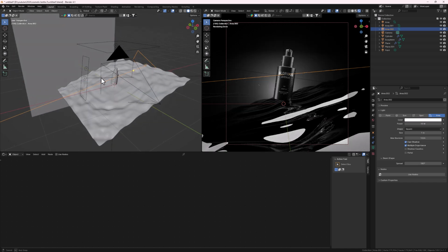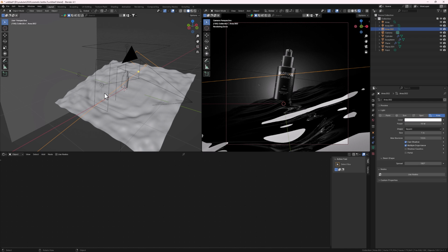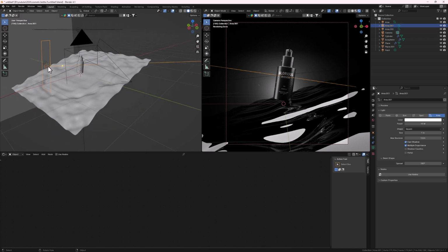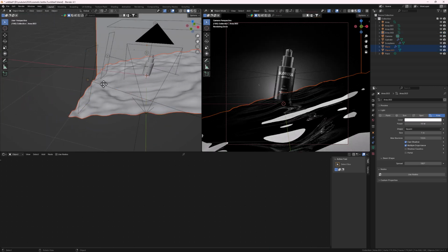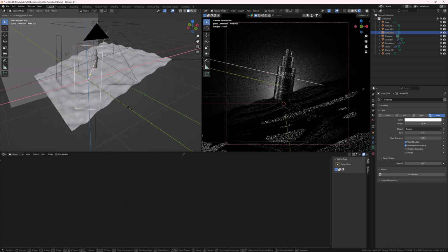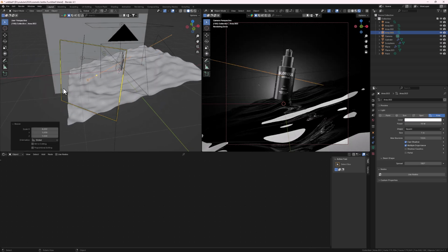Then maybe we can add a last one facing towards our area light. So let's select this, Shift D, now bring it to this side, and then with this selected, point it towards our object. Then maybe we can increase this main one like this, then maybe increase the power to, let's say, 50.